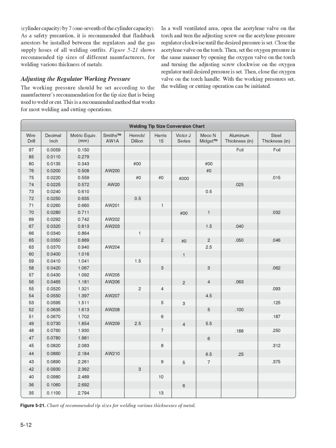Oxidizing flame. The oxidizing flame burns at approximately 6,300 degrees Fahrenheit and is produced by burning an excess of oxygen. It takes about 2 parts of oxygen to 1 part acetylene to produce this flame. It can be identified by the shorter outer flame and the small, white inner cone. To obtain this flame, start with a neutral flame and then open the oxygen valve until the inner cone is about 1/10 of its original length.